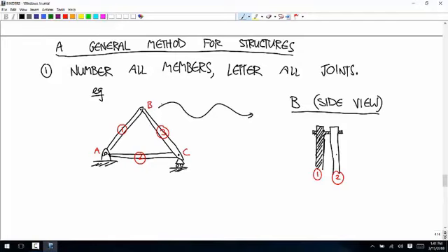And also, by the way, in deformation, what if that was a pin joint? It's not like anything crazy would happen. That's probably how you would build it. So it's sort of unsatisfying to think we just can't calculate it if there's a pin joint there. Well, we can, but you have to take into account the deformations of the material. There are ways to do calculations of things that are statically indeterminate, and in deformables we'll talk about how to do that.